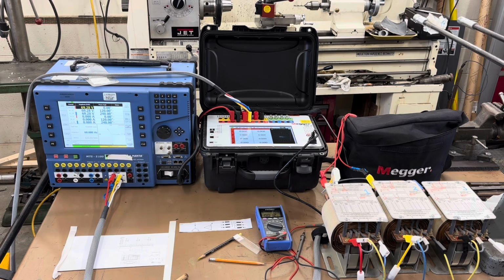So in this exercise, we're going to walk through the connections, make sure that we connect these transformers like this nameplate. We're going to apply voltage to the high side winding. That is ABC phase sequence. We're going to observe the phase angle relationship between the secondary and the primary and confirm that it matches the nameplate. And then we're going to switch things up, and we're going to swap the phase angles on our channel 2 and channel 3, or B and C,